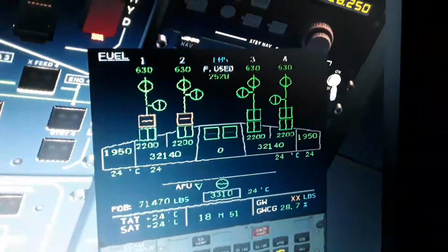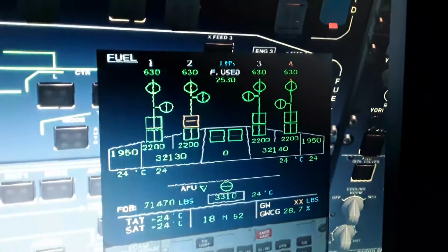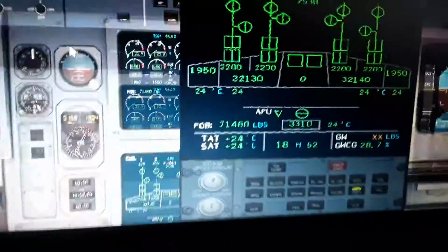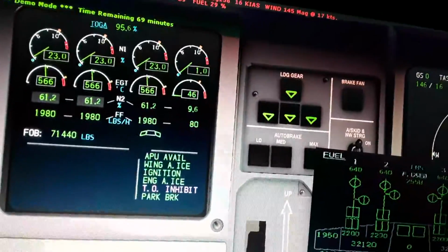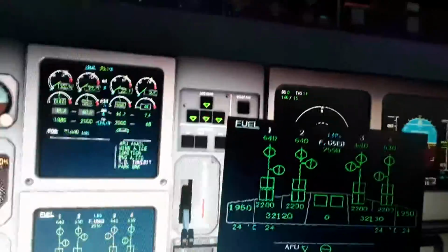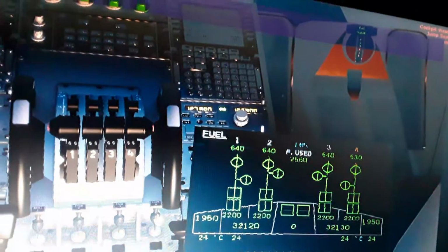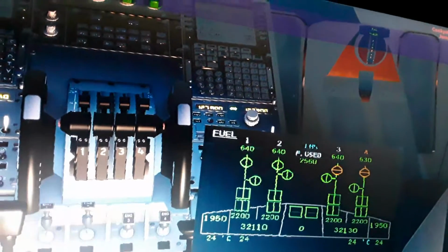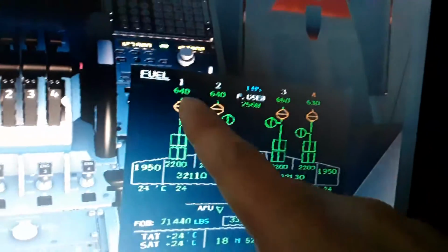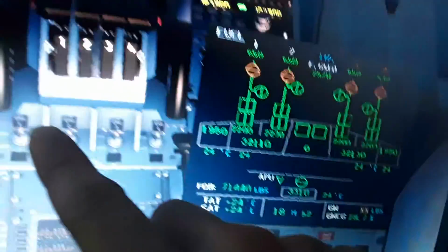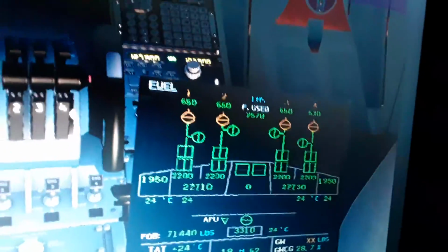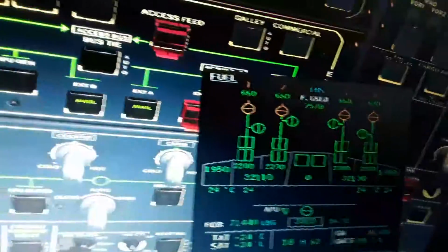We're going to have an engine failure like that. But I'm going to turn off the engines anyway. So we have engine number 4 right now. It's off. Now it started again. So I'm going to turn this switch off for the engines. All switches off, and you see here all the fuel valves are closed from these switches. There are 4 switches. You can see it here in the ECAM display. So we have no fuel in the engines right now.